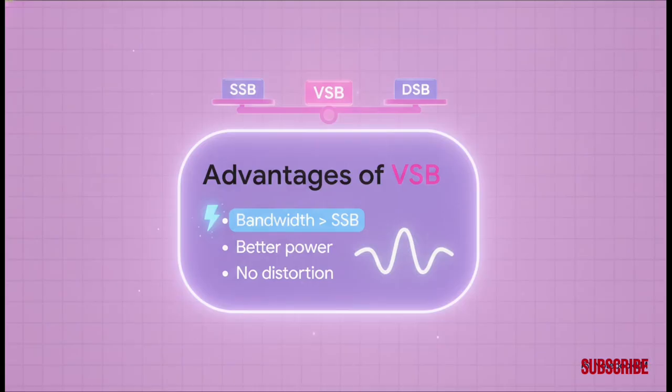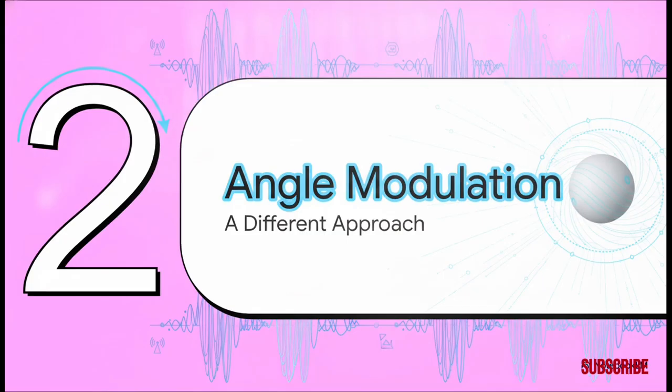That brings us to vestigial sideband, or VSB, which acts as the perfect middle ground. Think of it as the Goldilocks solution. It uses a bit more bandwidth than SSB, but less than standard double sideband. It gives us better power transmission, and most importantly, it provides crucial protection against phase distortion since there's no loss of frequency components. It's just a clever compromise engineers use when they need a little more quality without wasting too much space.